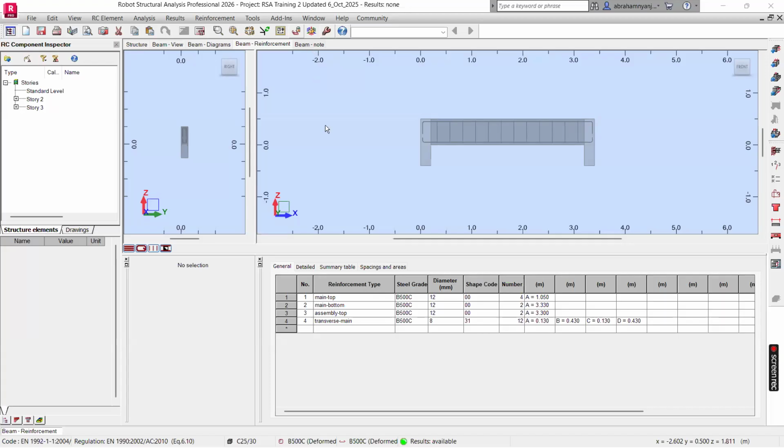I don't want to appear like I'm answering the previous question, but from what I understood, you cannot see the point load because what you are visualizing are the internal forces after analysis. To see the point load might be a bit challenging after analysis, but you'll see the effects of that point load. I think that's how I answered myself, but I'm eager to wait for your conclusive response on that.